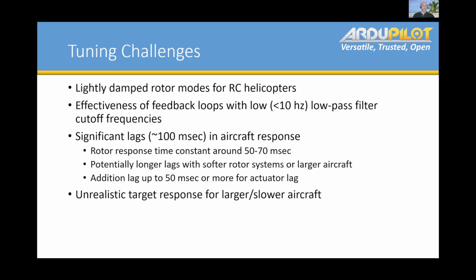And again, not only are the low pass filters providing lag, but there's also lag due to the aircraft response in nature, right? So the rotor response. I said that there's some phase lag between when the rotor sees that max cyclic to when it achieves the max flapping response, and that's kind of a steady state thing. There's still 2 to 3 rotor revolutions, depending on the aircraft, before it actually achieves that steady state of that tilt back. So that's around 50 to 70 milliseconds, the time constant for the rotor response. And you can see there's probably longer lags if you have a softer rotor system. But also there are these additional lags for things like actuator lag.